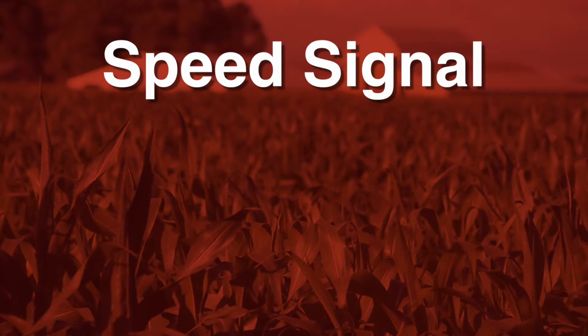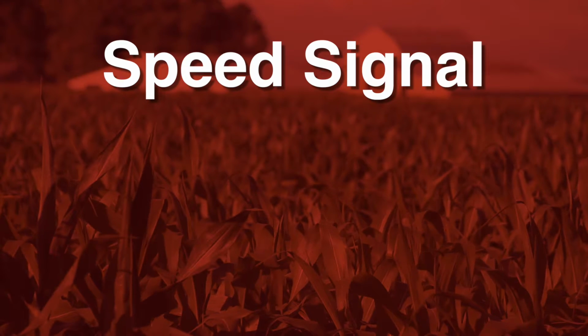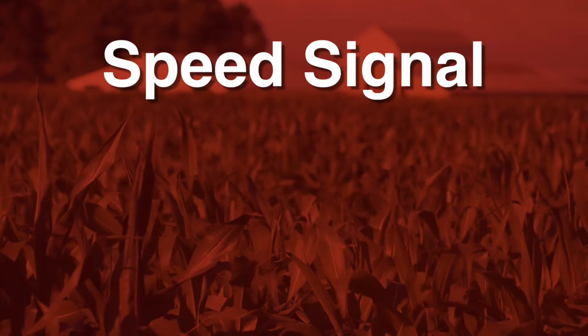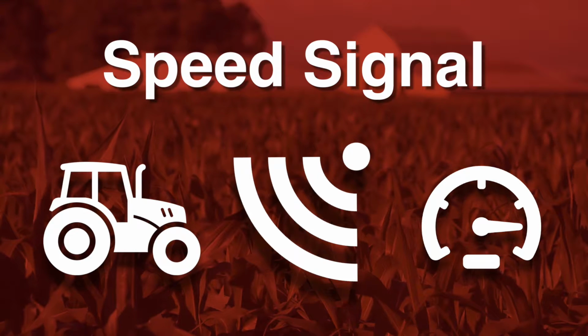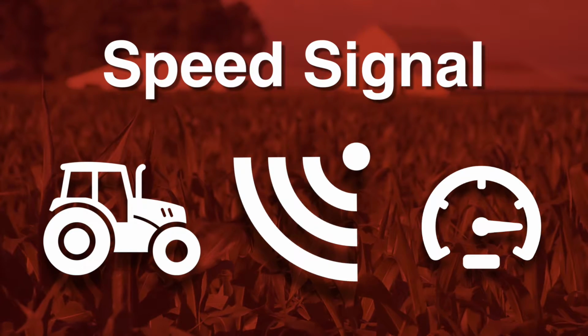Next, let's set up the speed signal. The speed of the vehicle must be known so that the ECU can calculate the application amount. There are 3 possible speed signal sources: the tractor, from radar, or simulated speed. Let's first look at setting up the speed signal with the source coming from the tractor.